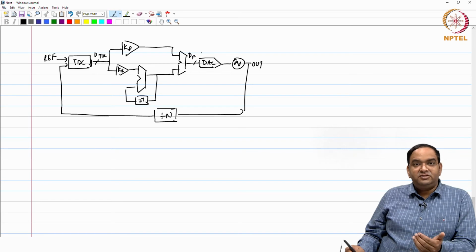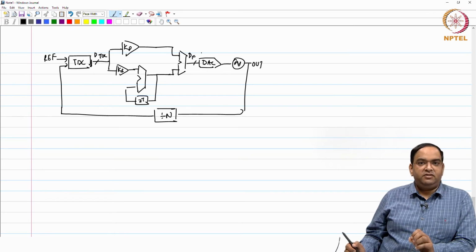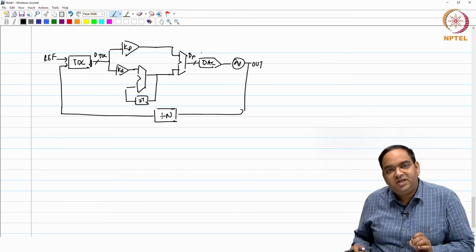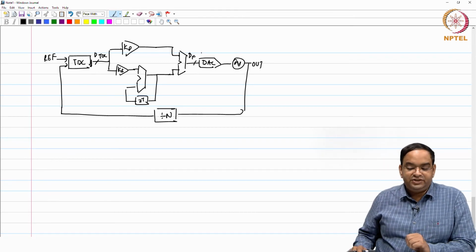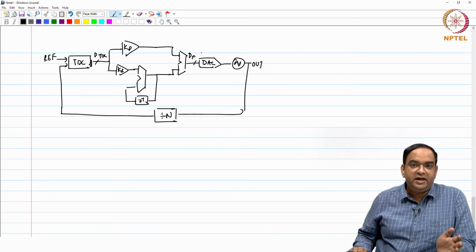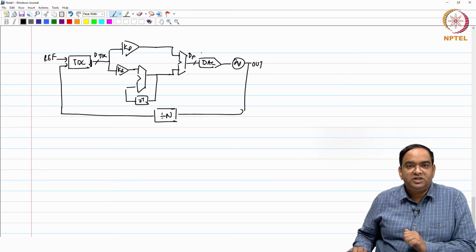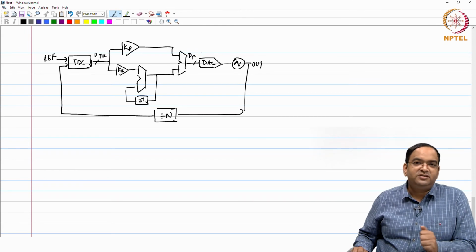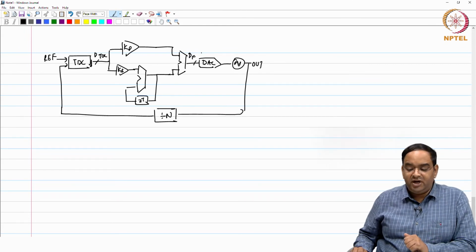When we did this, we found that the quantization noise of the TDC is one of the biggest problems for this digital stuff, and no matter the benefit which you have got by removing the loop filter capacitor and replacing it by the digital accumulator, TDC quantization noise is just spoiling the party.